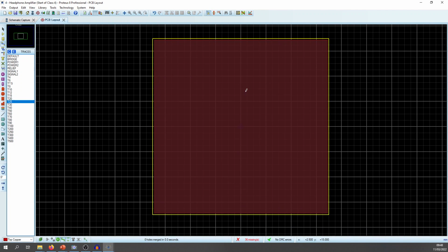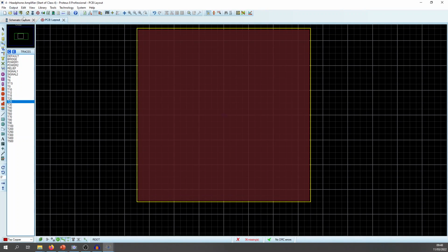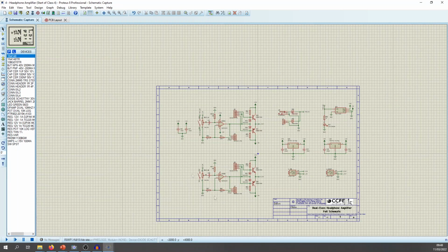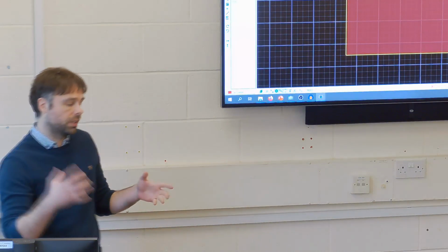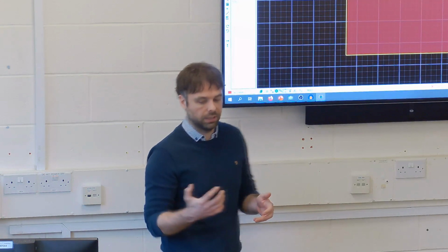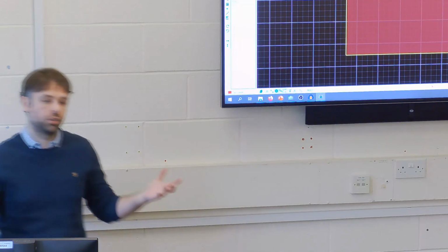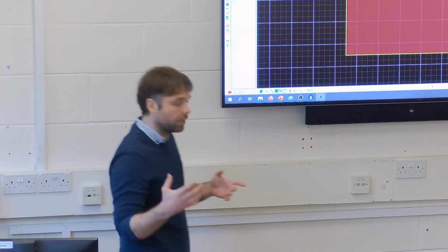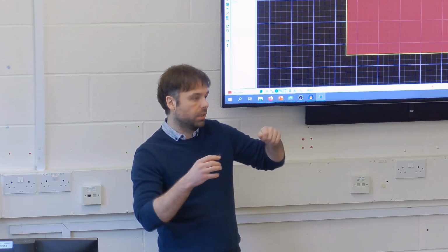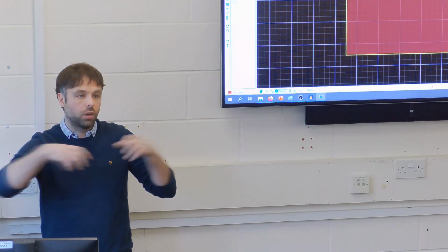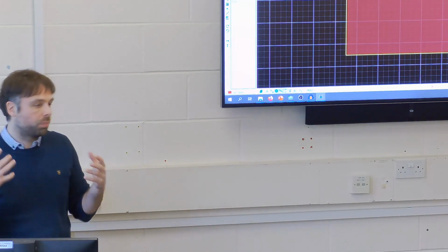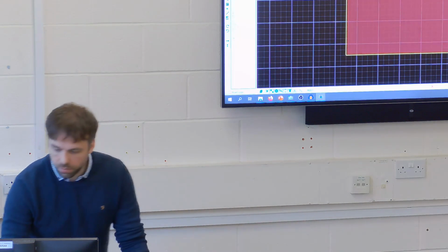Right, so we're getting there. We're close to having this board set up, ready to go. In fact, I think we are. So what do we do next? You've got all these components and you've got a blank PCB. Where do you even start? The first thing that you need to do is place all of the big chunky stuff, but more importantly, the mechanical stuff that can't move. So you're going to have mounting holes, I assume. With a headphone amplifier, you've got a volume potentiometer, or you've got a DC jack. Those things have to go around the edge somewhere. So place all the stuff that's fixed. So that's what I'm going to do.